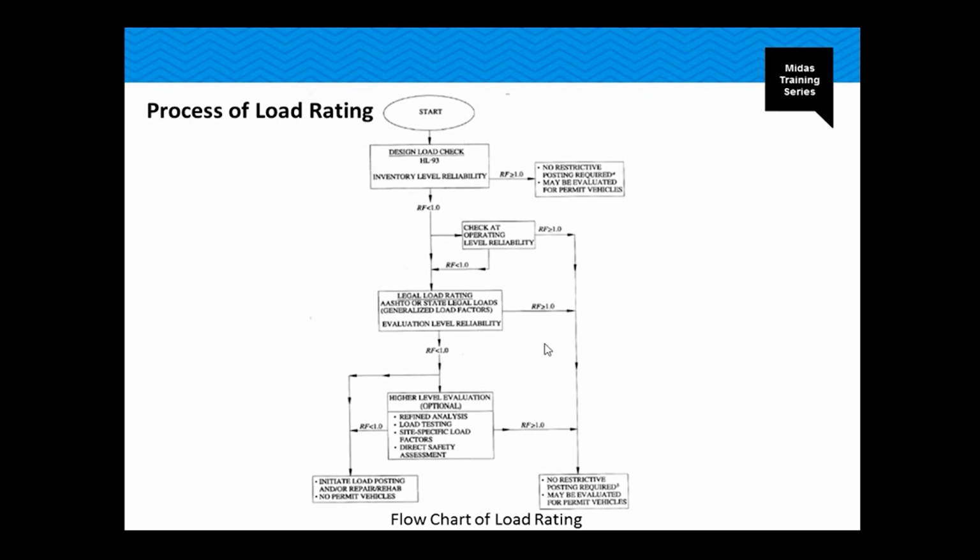If it goes okay with the legal load rating, then it's fine. If it does not, then we need a higher evaluation load rating. We might need the load testing, site-specific load factors, direct safety assessment, refined analysis, and there's where different types of programs come in, such as the MIDAS Civil and so on as well. You can also perform it for the design load check. It's the one that we're gonna see today.